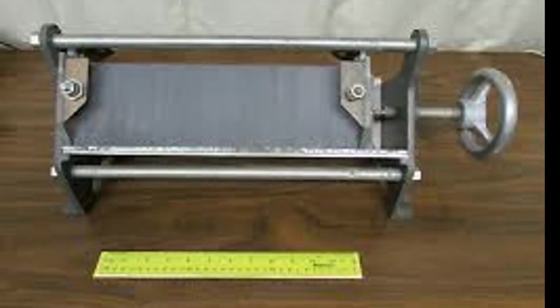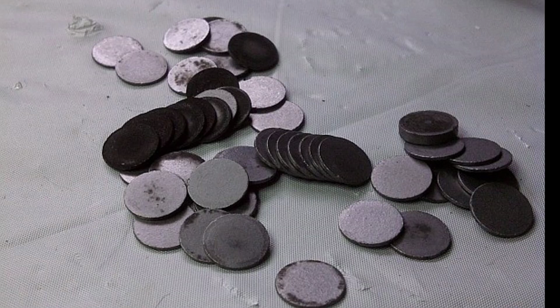Carbon pile. A carbon pile resistor is made of a stack of carbon discs compressed between two metal contact plates. Adjusting the clamping pressure changes the resistance between the plates. These resistors are used when an adjustable load is required, for example in testing automotive batteries or radio transmitters. A carbon pile resistor can also be used as a speed control for small motors in household appliances, sewing machines, handheld mixers, with ratings up to a few hundred watts.